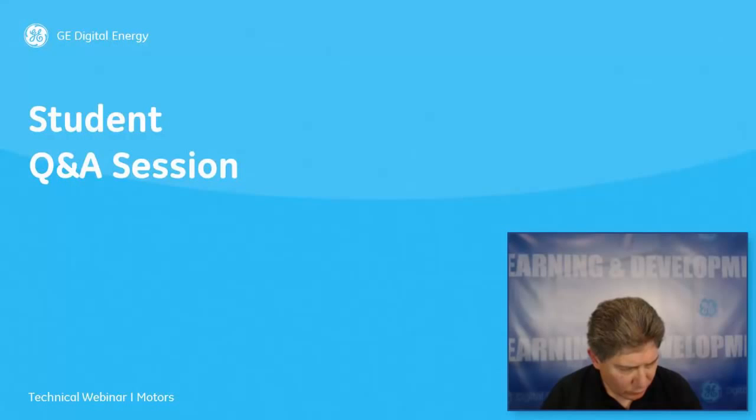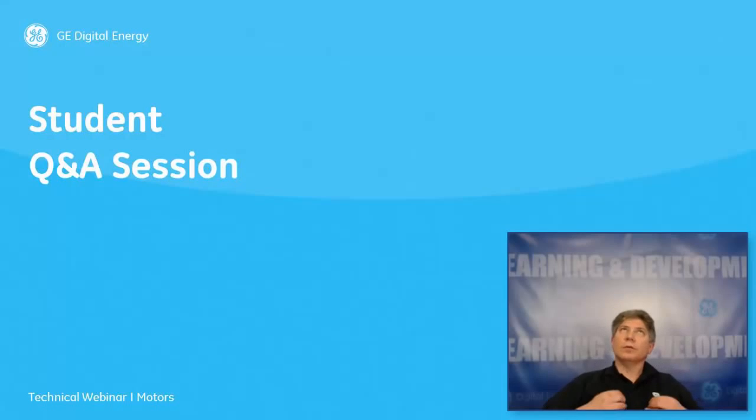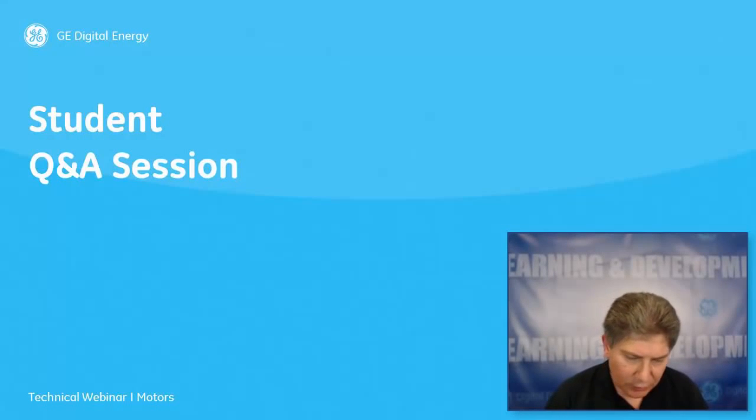It has nothing to do with the saturation. It has to do with the insulation to ground. So it's quite standard for switchgear manufacturers to use 600 volt class CTs. 600 volt class CTs in medium voltage? Yes. Okay, all right, my mistake then. Thank you so much for that.